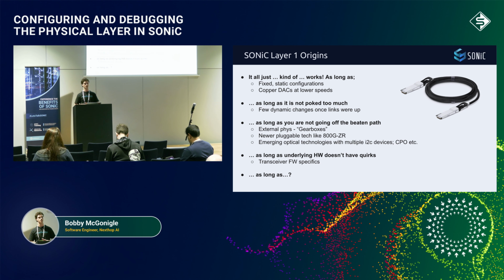So I talked about the internal PHY SerDes, and something like having an external PHY, where there's another PHY chip sitting in between the internal ASIC and the front panel. That can be there for a couple of different reasons. If there's too much trace loss, you might need to retime the signal. You might want to convert X number of lanes to Y number of lanes in the front panel. There are a few different reasons, but it just adds another configuration parameter, and those types of things diverting off the happy path didn't play well with SONiC's early origins.